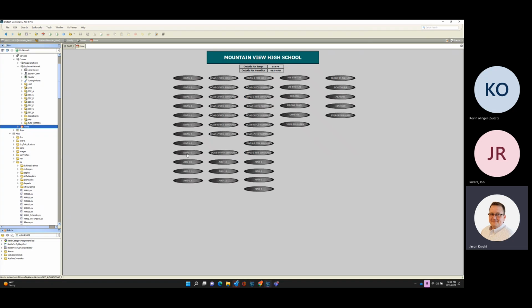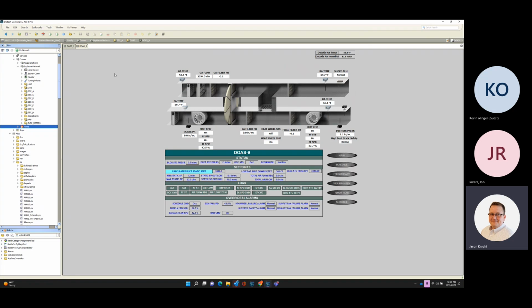And by features, I mean, when you look at the graphic, they may look similar, and they're pretty similar. The setup, the configuration is a little bit different with the heat wheel and whatnot. But the actuators on DOAS 5 through 9 are analog, meaning they're linear 0 to 100, and DOAS 1 through 4 are just digital commands on and off. I think because of the whole COVID thing and manufacturing process, they had to accept whatever was available as far as the units, and trying to keep everything standard has been super complicated with new equipment at this point.